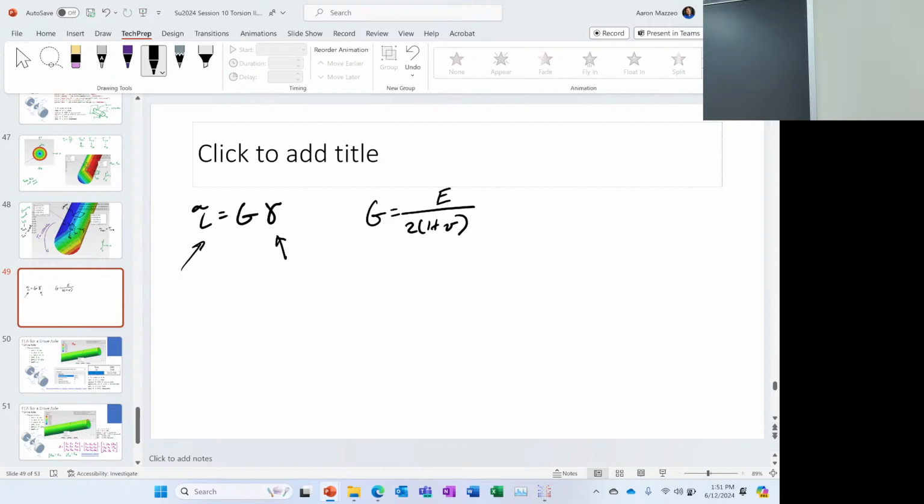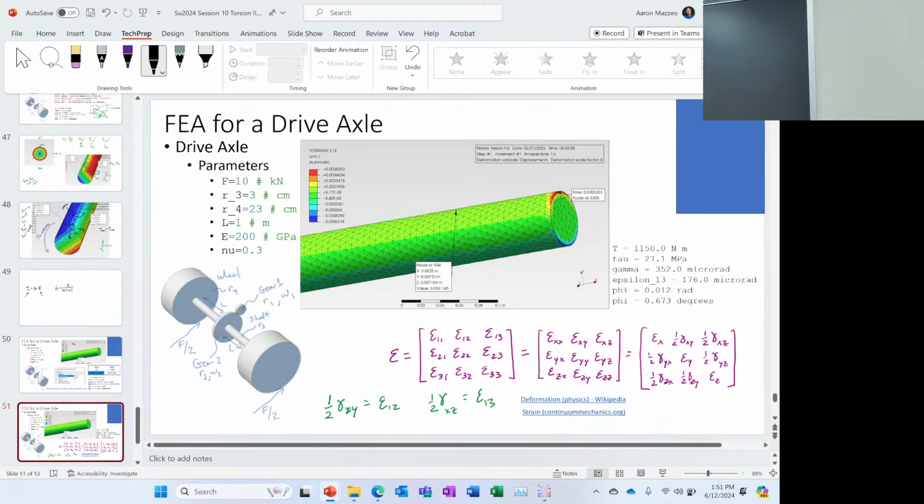There's a little catch though, okay? It'll come out a little bit more when we do the Mohr circle for shear strain and regular strain. What PrePOMAX and some software do is they use a tensor form for strain. In this tensor form, you can see epsilon is equal to epsilon 1,1, epsilon 1,2, and all these different components.